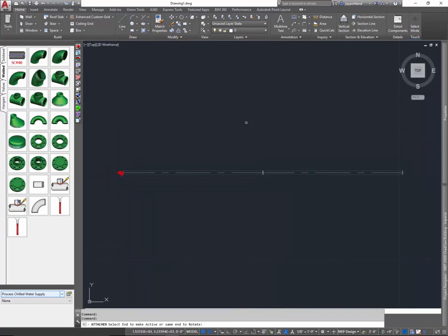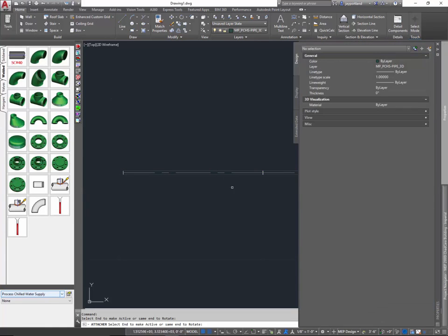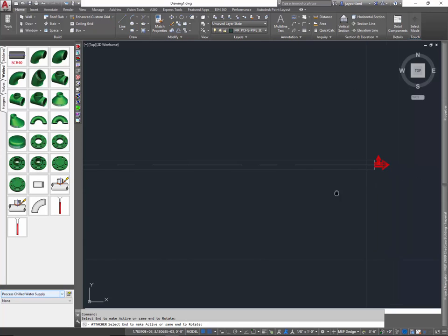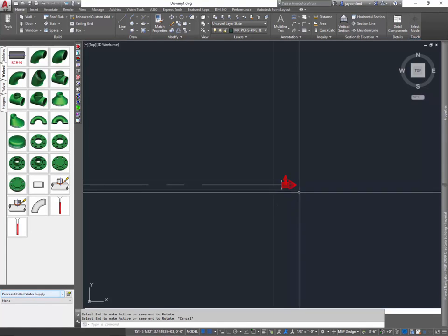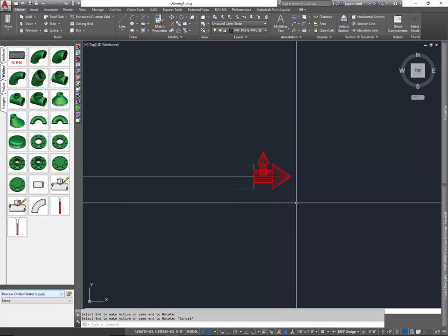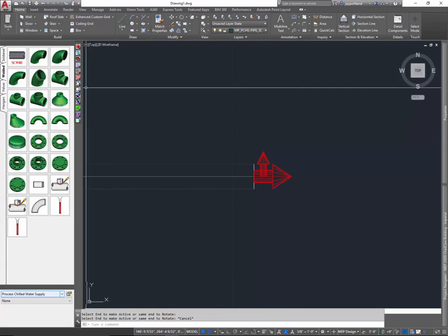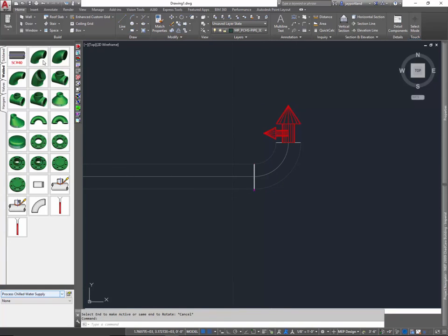Now you can move that attacher to the other end by using the toolbar, and maybe I want to add an elbow. Now the elbow that I'm about to add, I want it to curl in this direction, down this way. And you're going to see something curious about the attacher. It's pointing straight out from the pipe, but it has a smaller arrow pointing vertically upwards here. So what that does is it controls the elbow orientation, as you can see here, right? Now let's go ahead and undo that method here, and let's add the attacher back to that location.